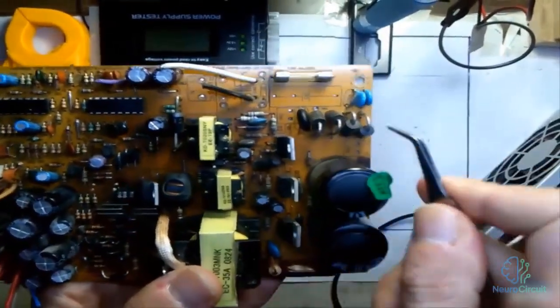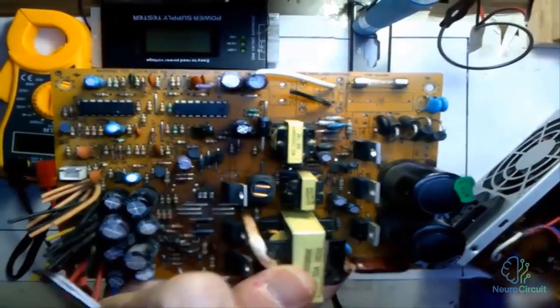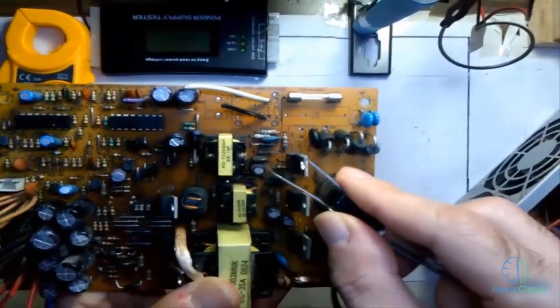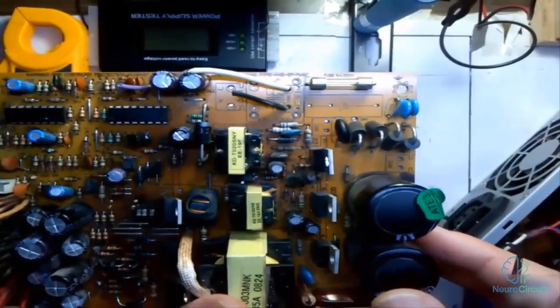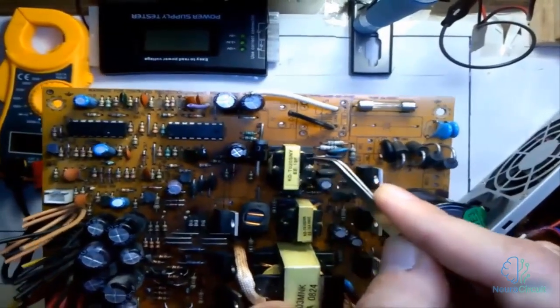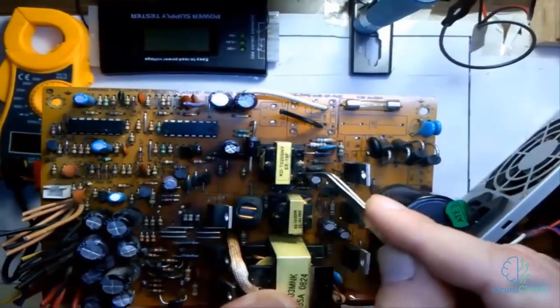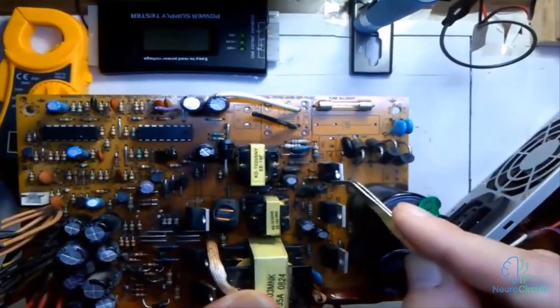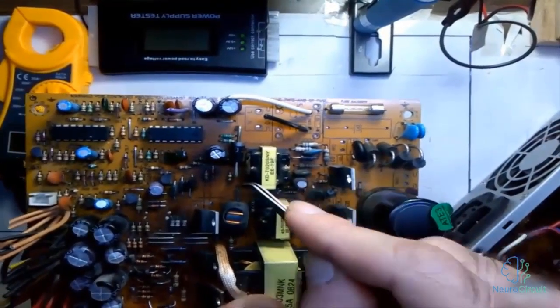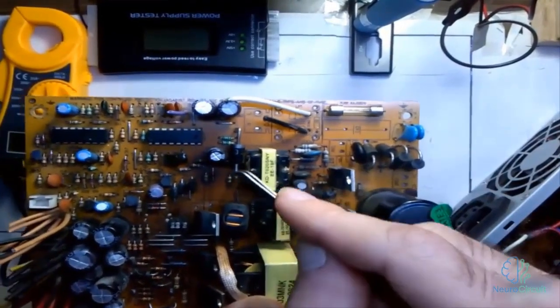Now, aside from the input path, the converter, and the output, we also have a circuit called the standby circuit. The standby circuit, if your power supply is plugged in, is always on. This standby circuit, which actually includes this section, as you can see, this part has more components, it's packed with them. That is starting from this first transistor, the first transformer and the components around them. These make up the standby circuit.